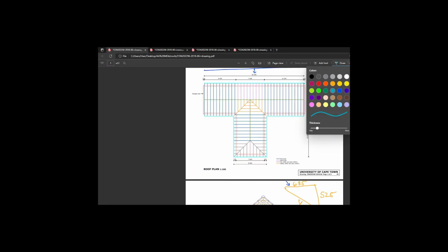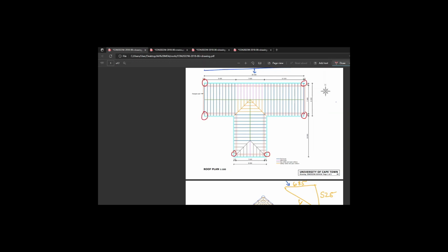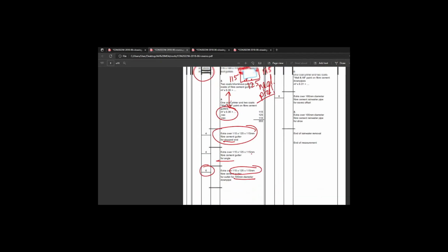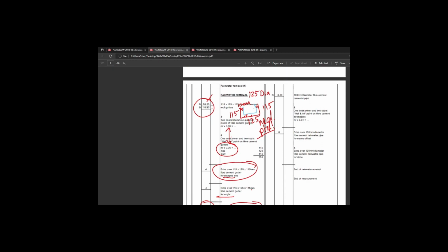I'm going to draw in red. There, I spotted 2. 1. Not so clear, but that is life. There are 6 outlets. Happy? Okay, downpipes. This is sometimes assumed. And 6 matches. That's 6 for the downpipes, one downpipe per outlet.